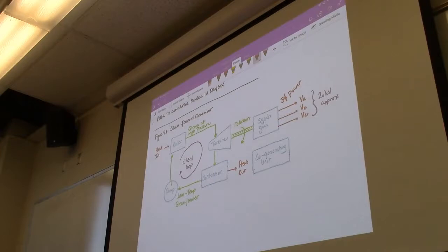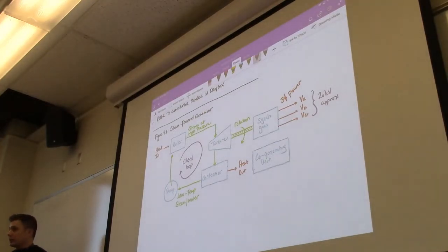More times than not, if this were nuclear or coal or something along those lines, it's not going to be anywhere really close to the loads that need it. So it's generated at a high voltage. It'll most likely, when it enters the transmission system, be bumped up to an even higher voltage and then transmitted over 50, 100, whatever miles is required before it reaches the load center.